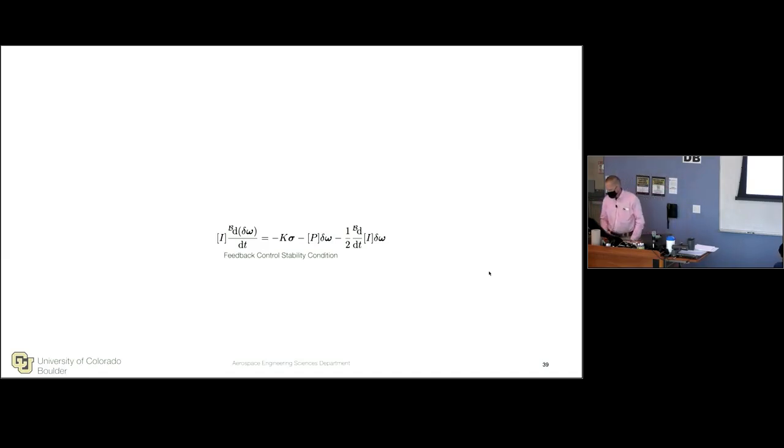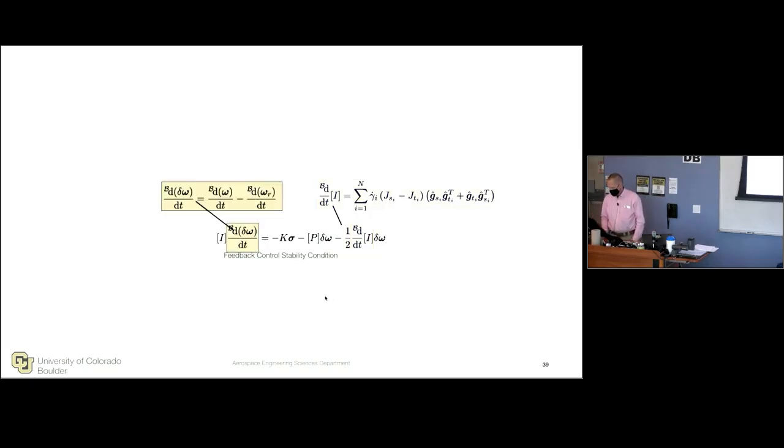Well, let's see what happens. We know all these terms. This one, I showed you the answer, and you should derive this yourself. We'd have to plug that into here. This part, we've seen in our earlier controls, delta omega, right? The B frame derivative of omega is going to be what in the end? Omega dot, right? Yeah, that cross product term drops out. But the B frame derivative of omega_R/N is not omega_R/N dot. There's an extra cross product term that appears, right? That's the transport theorem. We've done that several times, but that's what you'd have to plug in here.